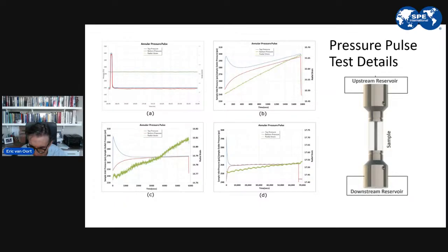Initially, when the barrier forms, the barrier is already as good as a cement barrier. So it will have a permeability of maybe a few microdarcies. But then, as you can see, as we go from B to C to D, and I hope you see the lengthening time scale, the shale permeability becomes lower and lower. And we've never done a test for months on end. That would be very expensive to do. But we think that ultimately the barrier will become the barrier with a permeability of the native shale, so in the nanodarcy range. And when it achieves nanodarcy permeability, the barrier is about 1,000 times as good as a cement barrier permeability-wise. And this is one of the reasons why I think shale make better barriers. This is absolutely crucial to verify the barrier, to verify its integrity, and you'll see a lot more of these plots in the remainder of the presentation.